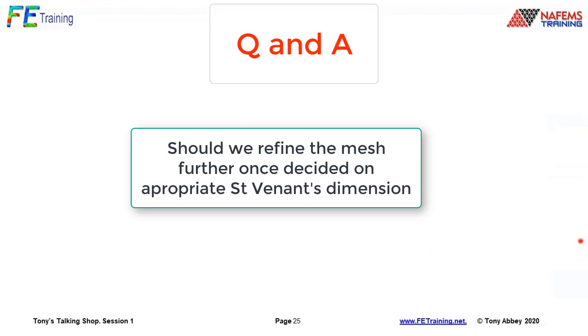And basically what I would do then is to put as many elements as I could within the limits of my machine, and then try to get that fillet radius in particular, of that shoulder, to converge in a stress convergence exercise. So the first approach, really, the St. Venant's idea, is to say that our element budget, which is perhaps a limit of our machine, let's put those elements where it counts around the shoulder region. And yes, exactly, Mike. I didn't go on and do a mesh convergence study, but that would be the next stage.